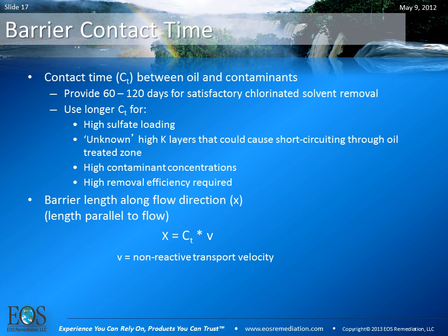Now contact time, barrier contact time. This is another important parameter. Again, the longer your oil and contaminants are in contact, the better chance that you have for treatment. So you typically want to provide between 60 and 120 days for satisfactory chlorinated solvent removal. You may need longer